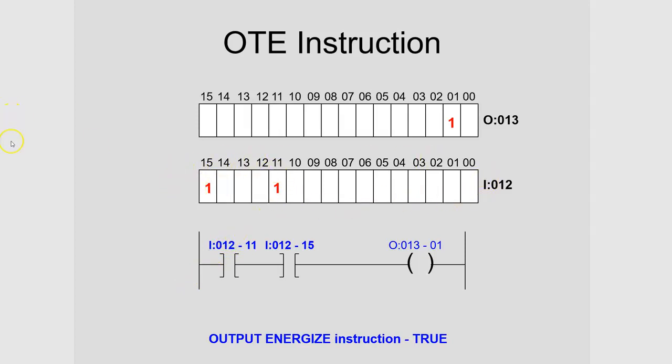There's 16 screw terminals out there on that input module, and if you count, there's 0 through 15, there will be 16 storage cells to hold zeros and ones that are mapped to those screw terminals, and they'll hold a 0 if the switch connected to it is open. It'll hold a 1 if the device connected to it is closed.